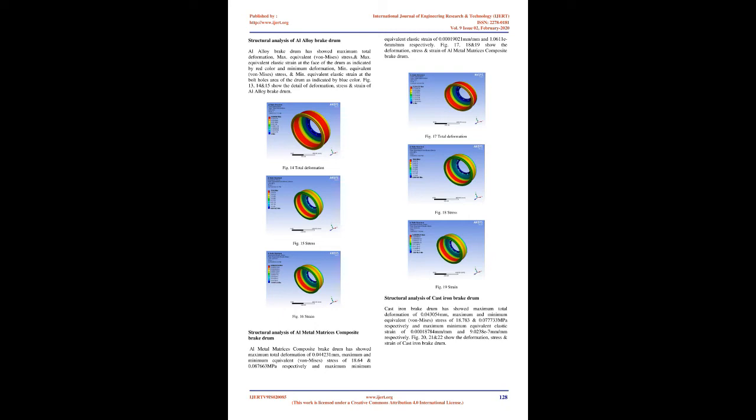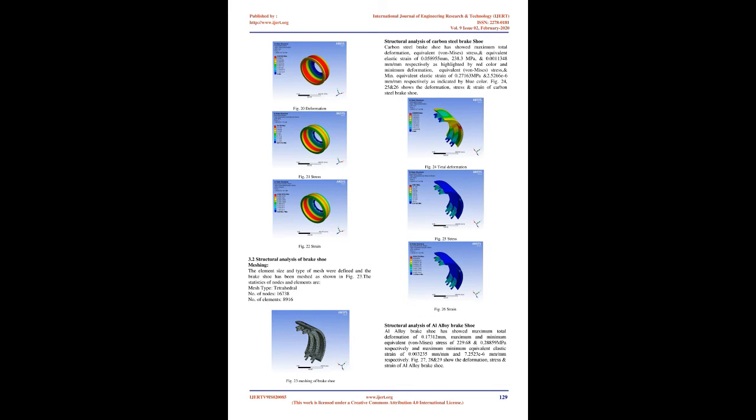2. Brake drum design. The design or capacity of a brake depends upon the following factors: the unit pressure between the braking surfaces, the coefficient of friction between the braking surfaces, the peripheral velocity of the brake drum, the projected area of the friction surfaces, and the ability of the brake to dissipate heat equivalent to the energy being absorbed. The brake drum geometry of this study is identified and its parameters are shown in Table 1.